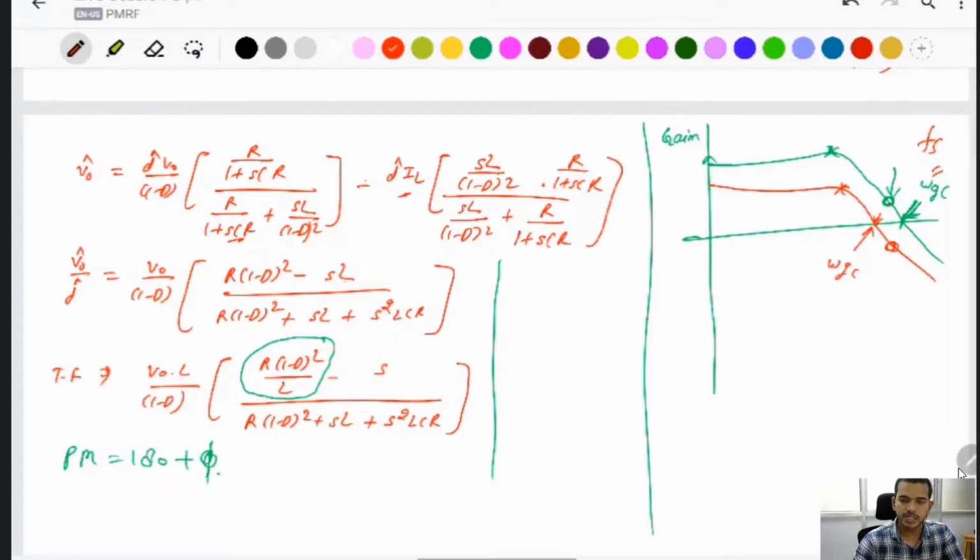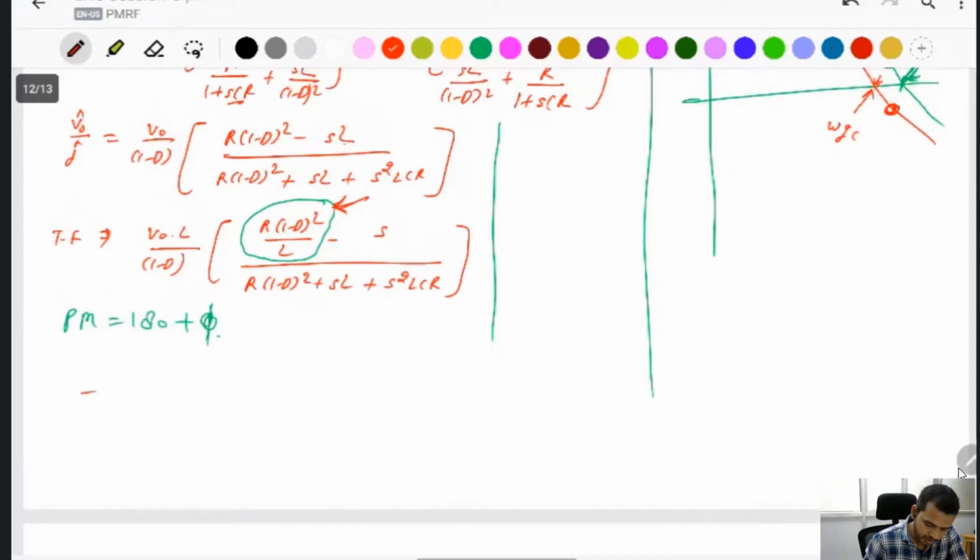And when you reduce the omega GC from the switching frequency, omega GC is actually taken like Fs divided by 10, I think 10 times less or 5 times less. That means the system should be in a robust and fast condition. And in the boost converter and buck-boost converter, omega GC is reduced even more because of this zero. The zero is present in the right half plane. To reduce the right half plane zero or eliminate a non-dominating factor like that, you should decrease omega GC in a range, like one third of this frequency. That is the thumb rule.